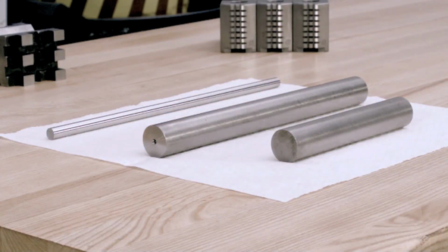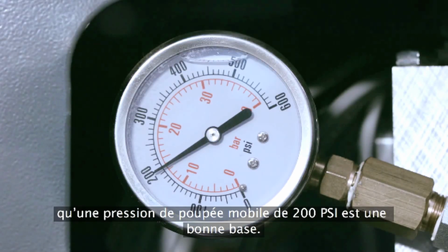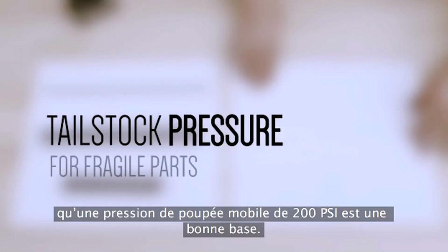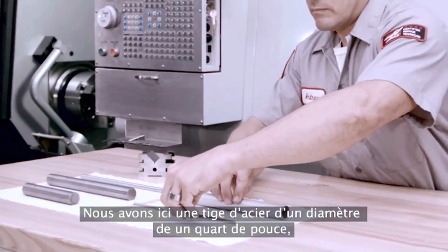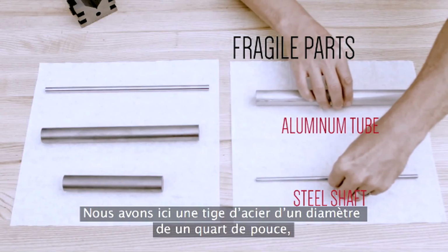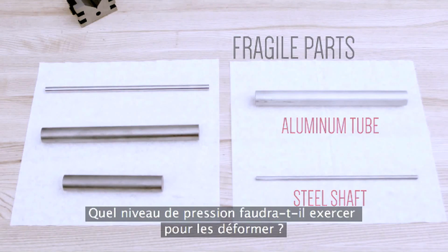But what about parts that deform easily? To recap, for stout parts, we just recommended a tailstock pressure of 200 psi as a good baseline. But with fragile parts, this doesn't always work. Here we have a 1/4 inch diameter steel shaft and a 49 thou wall 1 inch diameter aluminum tube. How much pressure will it take to deform them?